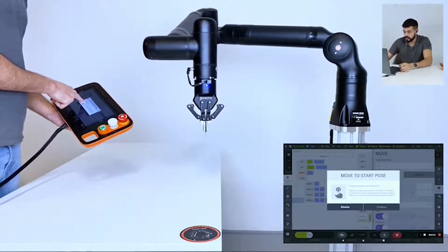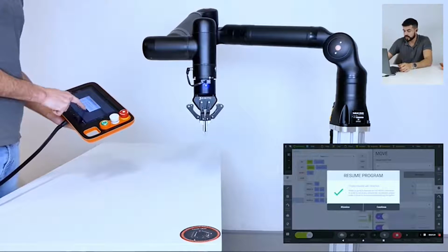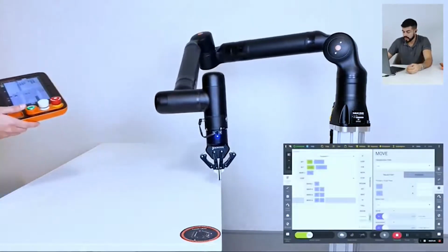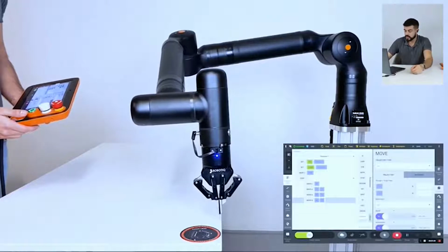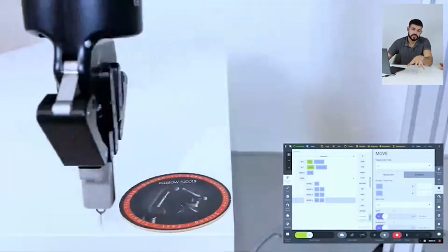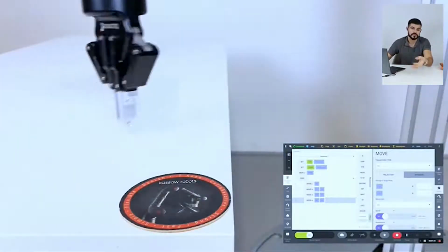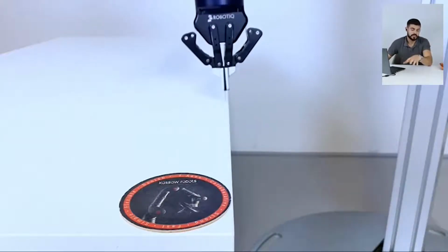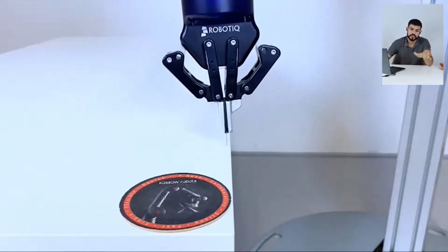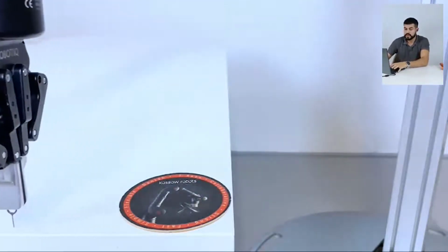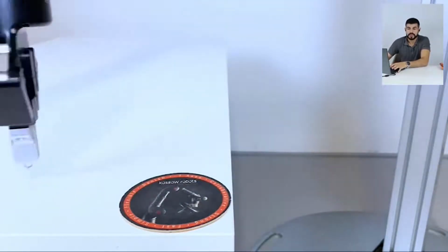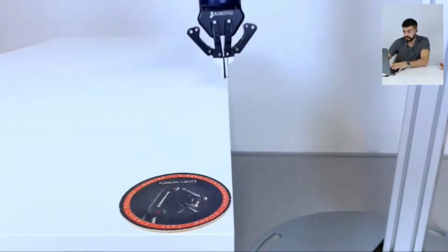The spline move is the same idea as the arc move that provides motion at constant speed. The difference here is that you can also define a curvature reference for your trajectory. So you can also perform constant speed, but also adapt the trajectory of the robot during the whole trajectory for different levels of surface, for example. We're also going to show you an example using the set file in another video.